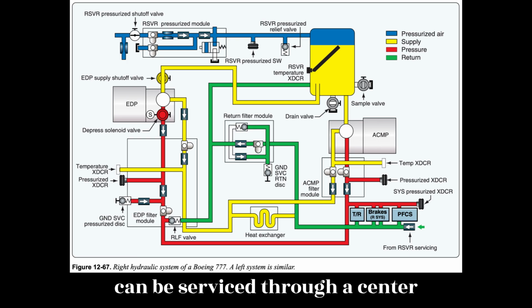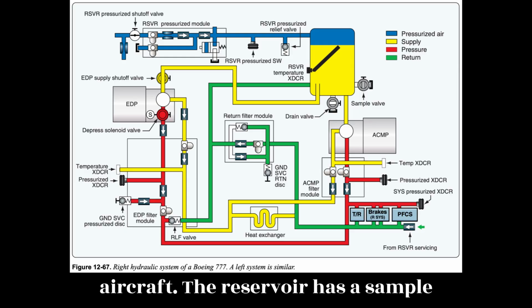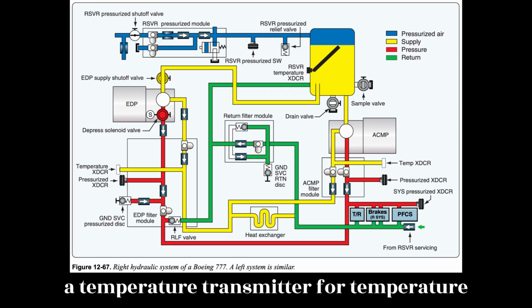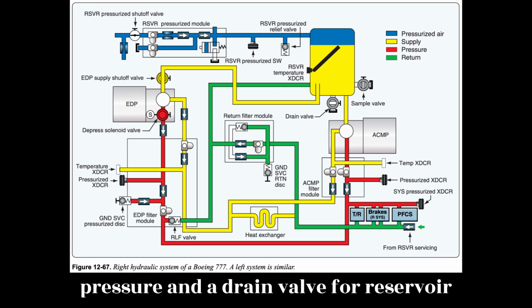The reservoir can be serviced through a center servicing point in the fuselage of the aircraft. The reservoir has a sample valve for contamination testing purposes, a temperature transmitter for temperature indication on the flight deck, a pressure transducer for reservoir pressure, and a drain valve for reservoir draining.